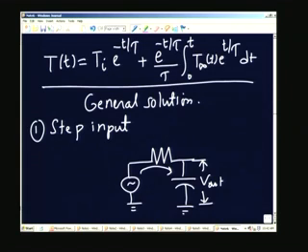Okay. So, there is the transient. The transient is when the capacitance is getting charged. So, what is the equivalent in terms of thermal system? In the thermal system, initially the temperature of the system is different from the temperature of the ambient, and once we communicate the two at t equal to 0, the temperature of the system or the thermometer will start going towards the temperature of the ambient, which is a constant value, and therefore, the temperature will approach it as t tends to infinity, as the time becomes large compared to the natural time constant of the system, much larger than the time constant of the system, the two temperatures are going to be the same.